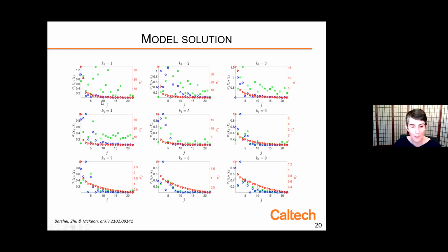As you go up in the SVD for this mode and the resolvent itself, this is the roll off of the singular values. And this is sort of at the heart of why the resolvent approach is effective, and that is that there's a severe roll off in the singular values. That is to say, there's a band of disturbances that are amplified, and there's a whole load of modes that are either in the null space or very close. They're just not amplified.